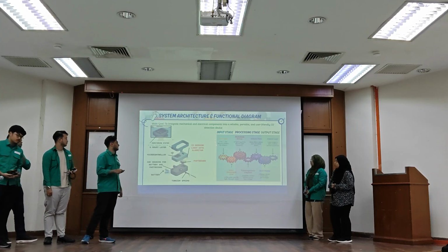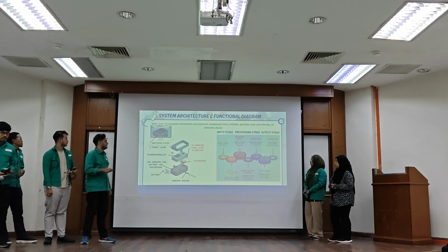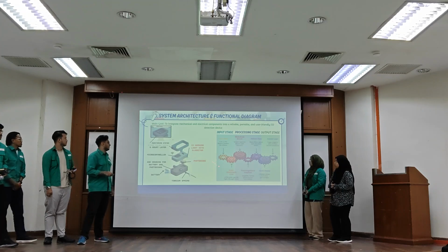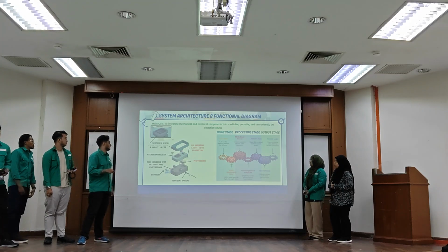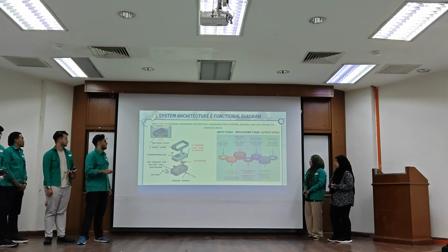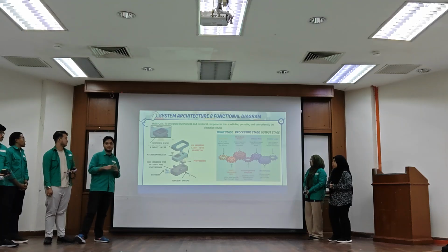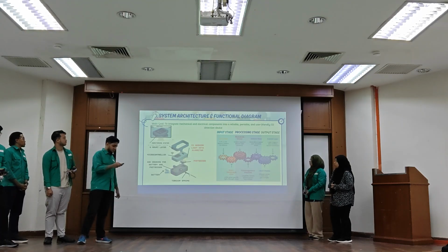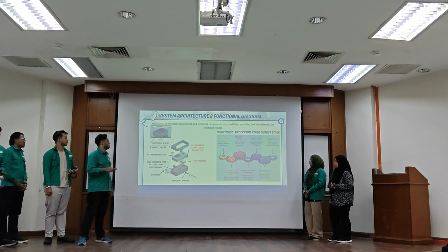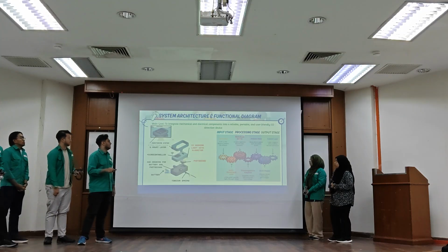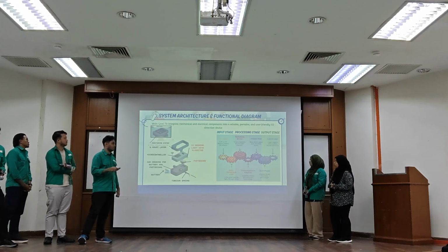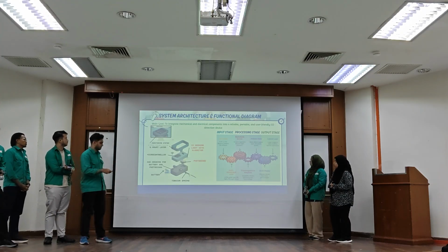For the stages, we have 3 stages. The first one is the input stage, where our multi-wavelength light is emitted from the LED and penetrates our skin. After it penetrates, the measurement is taken by the photodiode, calculated by the Arduino, and displayed on the display.